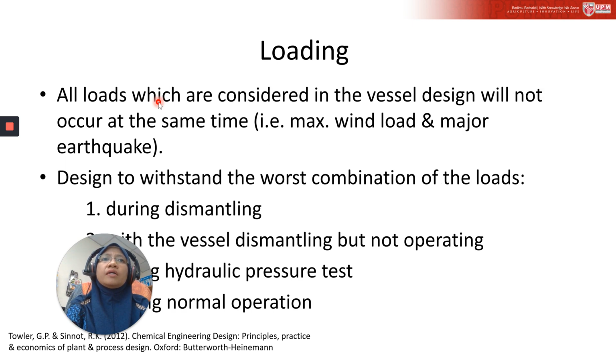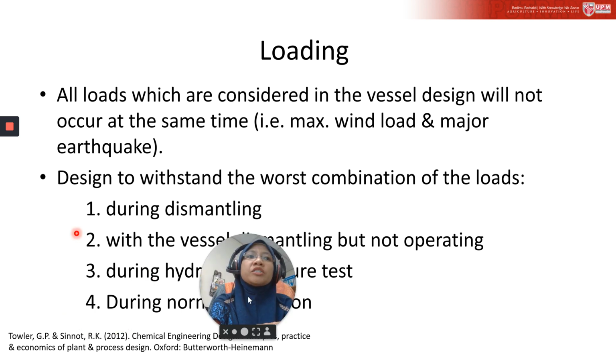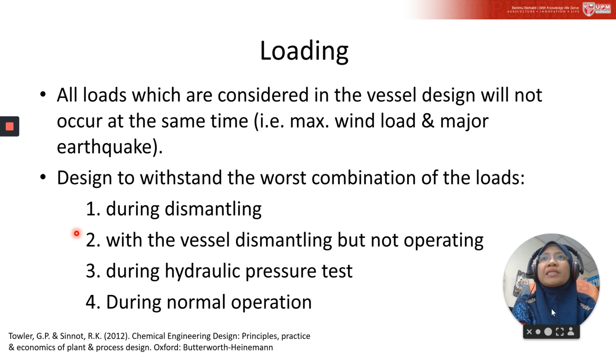And then for loading, the loads to which a vessel may be subjected will not all occur at the same time. For example, the maximum wind load will not occur simultaneously with a major earthquake. So you must design the vessel by taking into consideration combinations of loads. For example, during dismantling or erection of the vessel, or with the vessel erected but not operating. Third, during the hydraulic pressure test, and the last one is during normal operation.